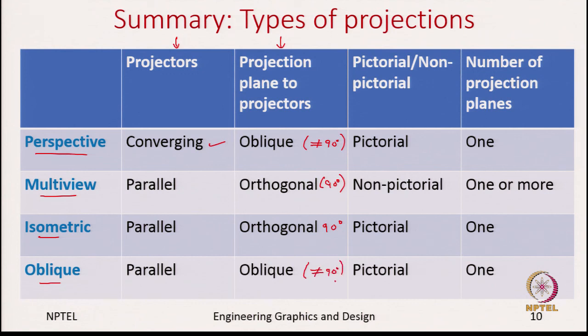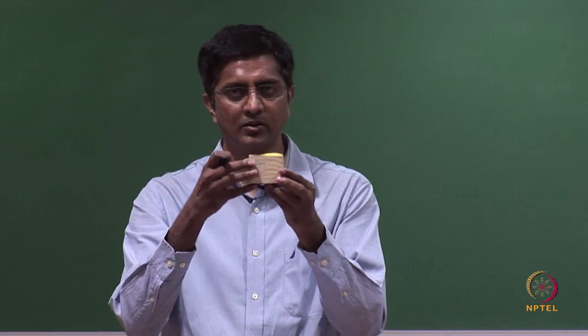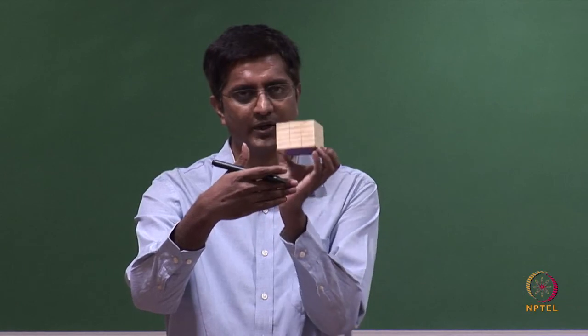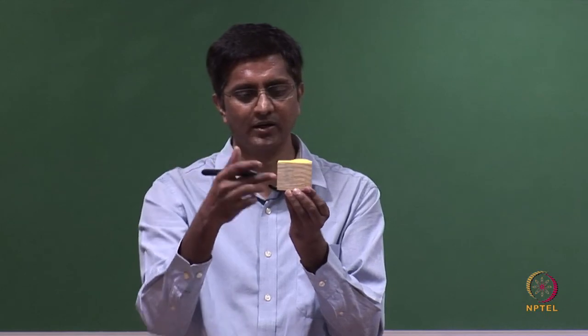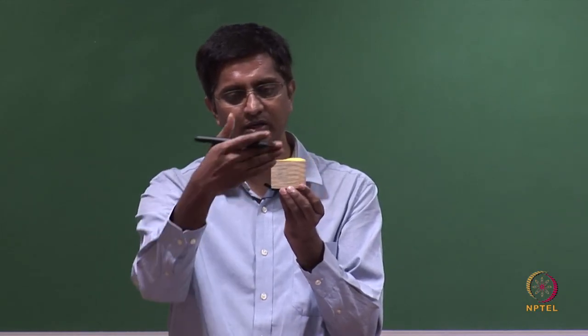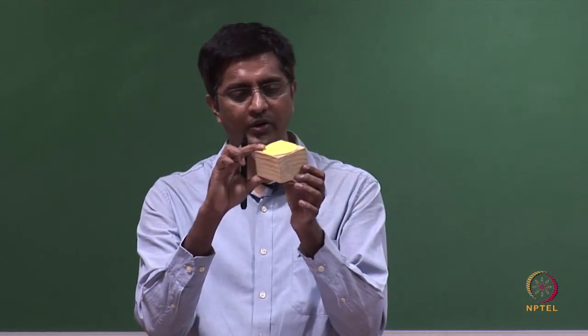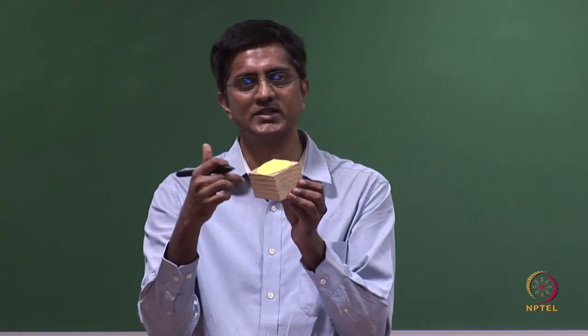And lastly, it is very important to say how the object is oriented with the projection plane. Only in the multi-view do you have this properly aligned. Either it is parallel to the projection plane or perpendicular to the projection plane, depending on which face you are looking at. If you are looking at the front face, it is parallel. If you are looking at this face which is on the side, it is perpendicular. However, in the other 3 you can hold the object at an angle where you can look at more than one face at a time.